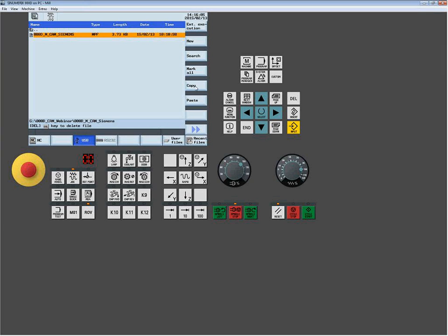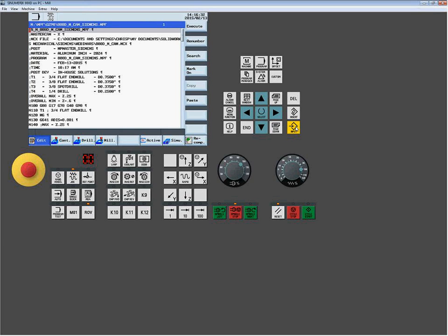I highlight the program, copy, and select it's going to leave me at the folder I passed in. So now I can simply hit Paste, moves the program into the part memory. So now, if I back all the way out, I'm back at the root directory, if I went to the G290 folder, I see this part program. Okay. To open up a program, just simply highlight it and press your Input key to start editing.